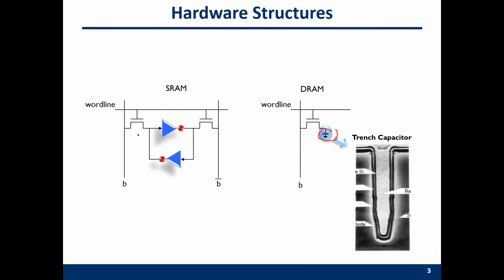When we activate this word line by setting it to 1, this gate is closed, so you can send the current or charges through this gate into this capacitor. This capacitor can store some charges for you. If it has those charges, then it's 1. Otherwise, if it has nothing, then it's a 0.